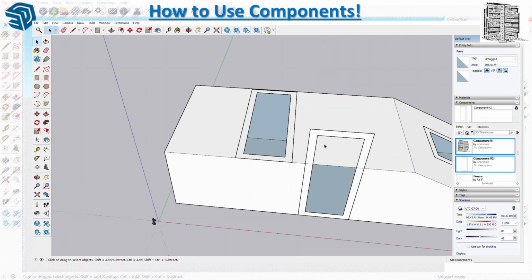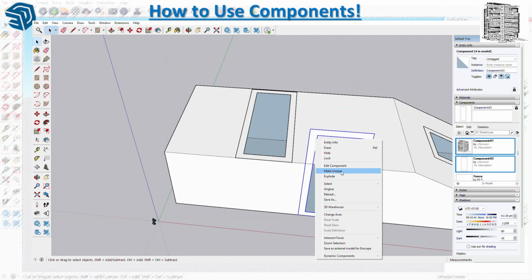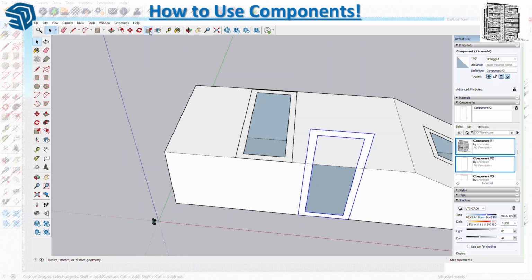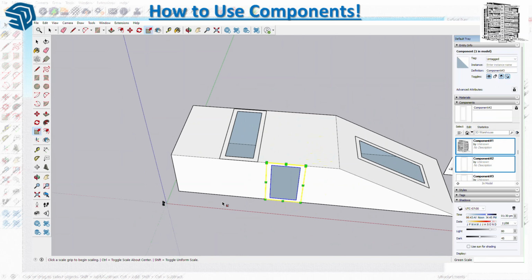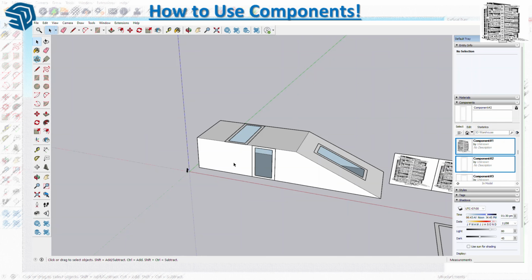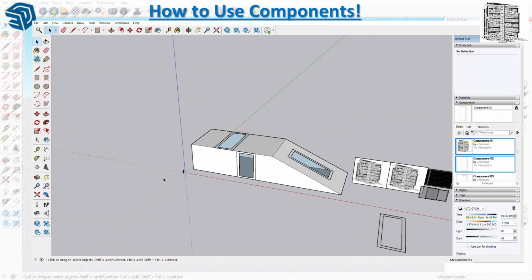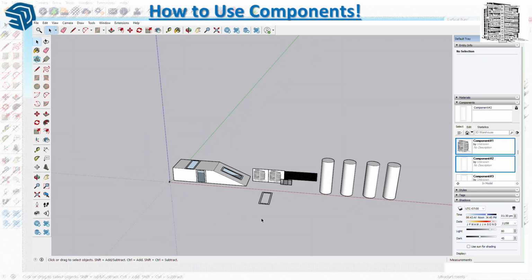But we did try this. If I want to only look at this one, I make this unique and then go to scale and only adjust this one that I have. So right now, I'll be able to have only this one in a different size from the other two. I think this is a great tool to use these items and create openings for windows, doors, any slab opening, column location or whatnot. You can use that.